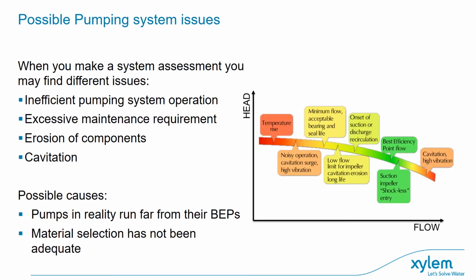Now speaking specifically about the pumps, we were saying that the pump performance might be lowered also by a number of losses in itself, in the impeller, in the casing, which might be mechanical and hydraulic, both affecting flow, head, and power consumption of the pump itself. So all the performances.